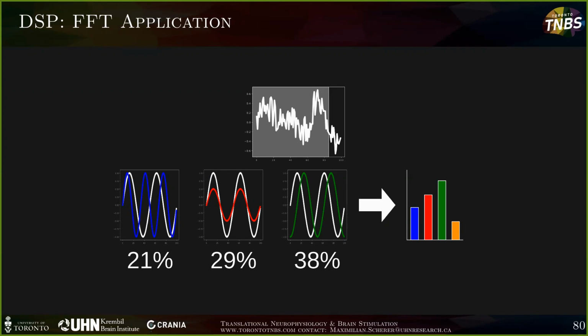And in the case of the FFT, that more output means that you're going to have a finer granularity in terms of your frequency bins. If you have a very shallow window, provided with very little data, you're going to have super wide frequency bins, like let's say 5 Hertz wide frequency bins.